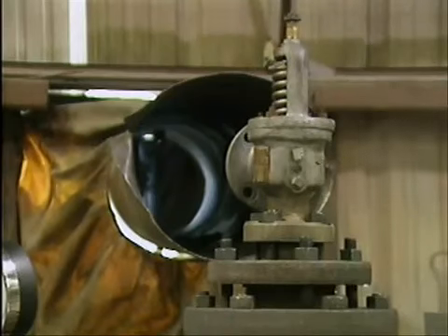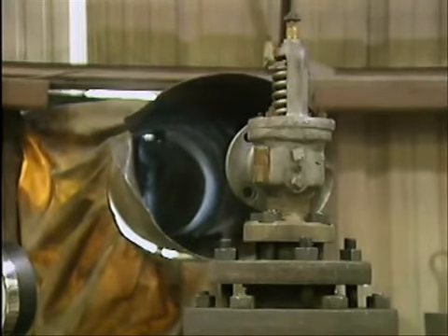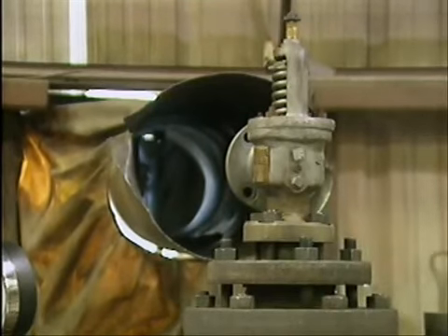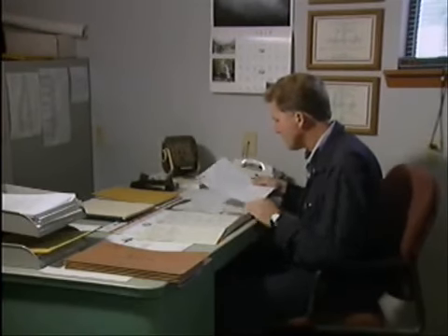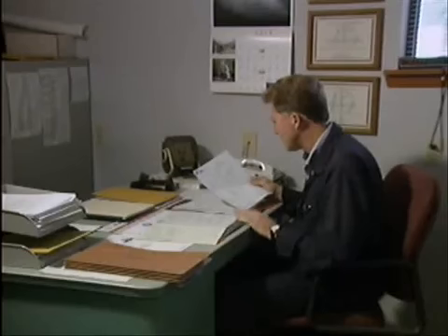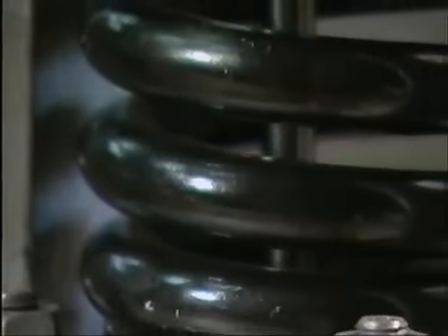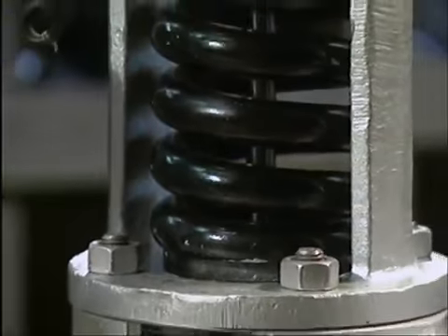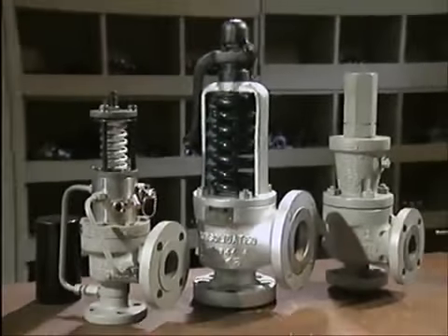After the valve closes, repeat the inspection procedure to check for leaks and more heat than would normally be expected after hand lifting. If the valve seats properly after lifting, it should start to cool down immediately. If the second inspection indicates that the problem wasn't solved by hand lifting the valve, or if hand lifting wasn't a possible solution for the initial problem, you'll need to follow your plant procedures to have the valve examined and the problem corrected. If an external inspection of a safety valve reveals problems, you'll usually need to disassemble the valve and inspect its internal components.